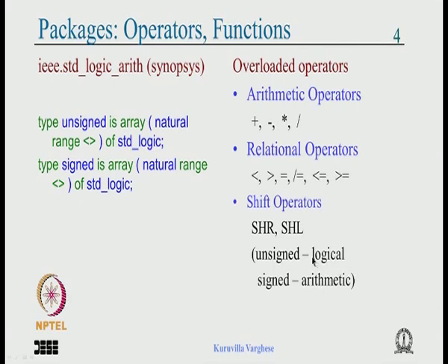So if you have a 2's complement number and you write shift, the sign bit is shifted along so that the value is correct for that width. That is the basic idea in signed arithmetic. Basically it is something to do with the right shift, not the left shift. Okay.